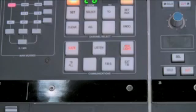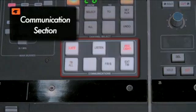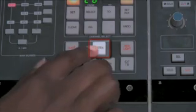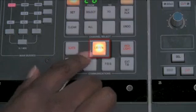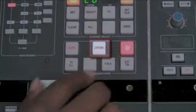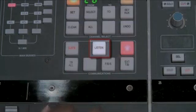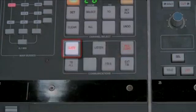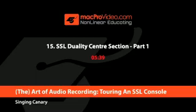Above the trackball, you find your communications section. This is where you assign talkback to your artist in the live room, as well as activating the listen option. So if you have a listen mic in the live room, in order to hear what the artist is saying without having them step right up to the microphone, you activate this via the listen option. The listen mic can be patched in via the listen mic input on the Patchbay. The slate option sends your talkback to all the outputs on the desk.